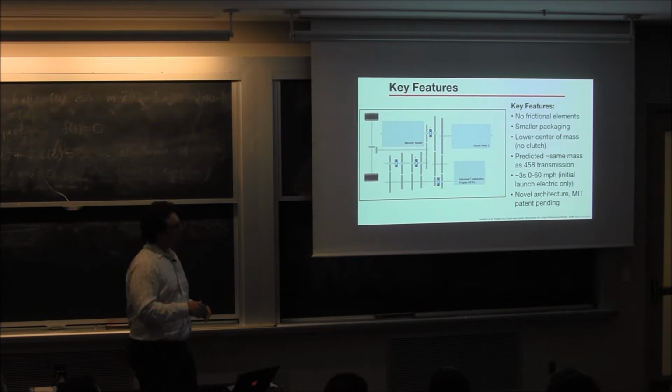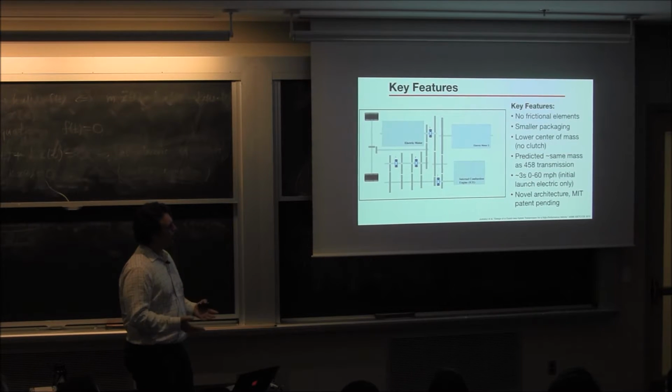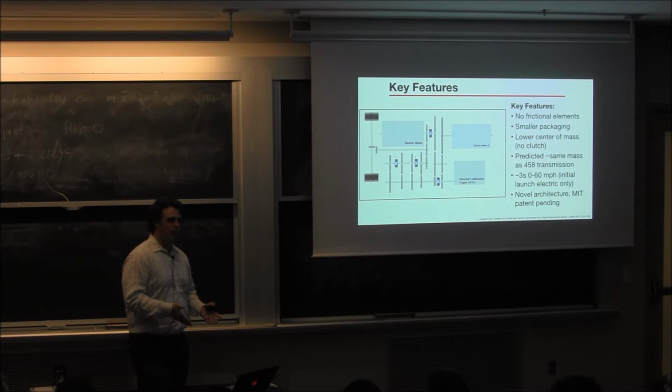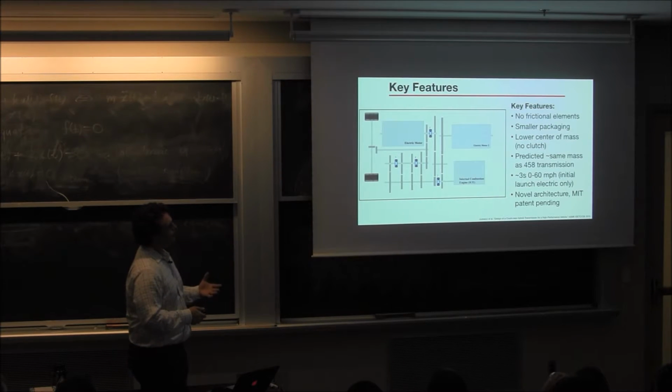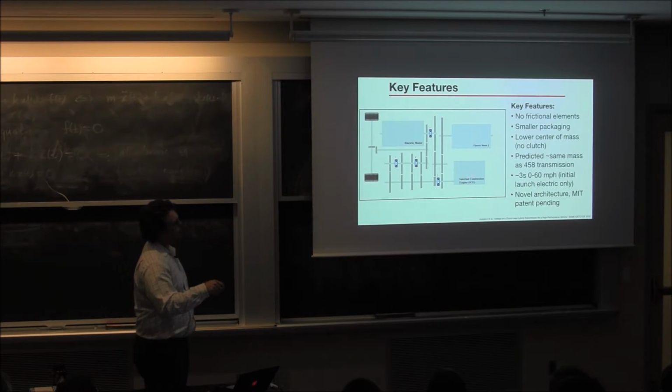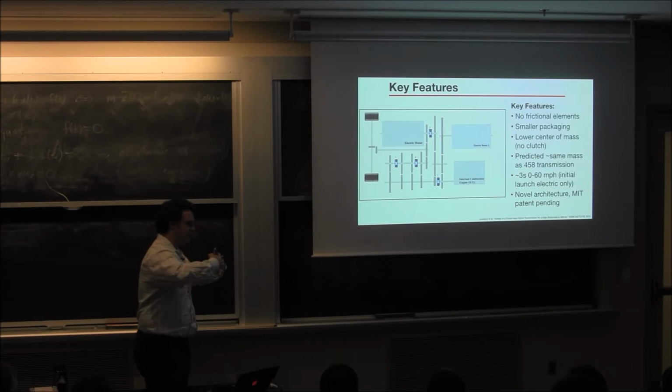And then they came back and thought about it, and they were like, wow, we would have never thought about this because we're a car company and we always think a car needs to have a clutch. But the reason we can get rid of the clutch is that when we want to shift into a gear, here's the transmission, and here's the gears, like 1, 2, 3, 4 gears you'd shift between. When you need to shift into a gear, you use this motor to match the speed between the driveline coming in and the IC engine coming in. So they move at the same speed, and then once they're at the same speed, you click into gear.